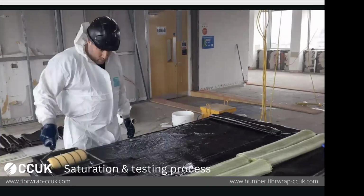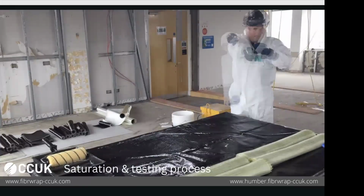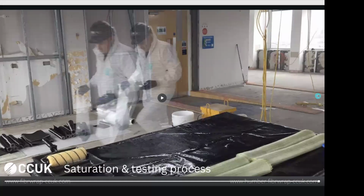So after saturating this piece on both sides, he will wait, as you could see here. So what you're seeing is the dry weight of the fiber. After saturating, he has taken the saturated weight. So it tells you the amount of epoxy he has used in saturating that piece prior to applying it in the actual area. So that way, you can make sure that the application is actually done as wet layup method and not dry layup.